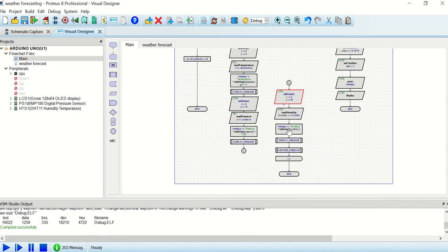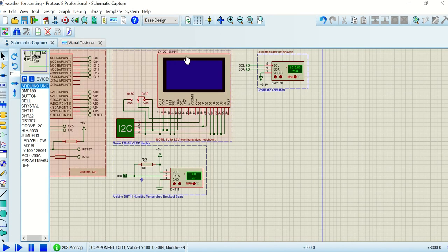Okay. Next, we can see another difference here. For each and every variable to be displayed, you have set the cursor differently, in the loop execution side instead of the display. In the display, if we set a cursor by default, that is basically for showing one line, but we have 4 lines here. First for reading the temperature, second for the pressure, next is humidity, and the last one is for the weather. So we have 4 messages to display. If we select the cursors manually, then you can make some difference in this output side as well, you know.